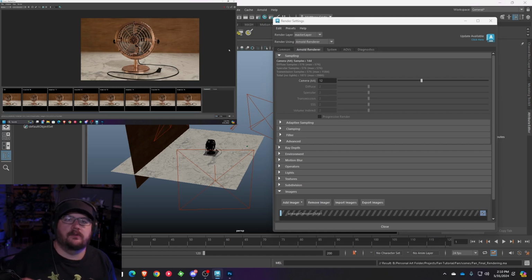One thing I'd like to put here is when you're rendering with a GPU, your sampling is a lot different, so you do have to increase samples pretty heavily. With CPU, you have a little bit more control over what samples you're increasing, so if you find that you're getting a lot of speckling in your reflections, you can change your specular samples over your diffuse samples. So if your diffuse is looking fine, you can leave those alone. The difference between CPU and GPU rendering in Arnold is small; there's a couple of little things to nitpick there. I like GPU rendering just because it is still generally faster.